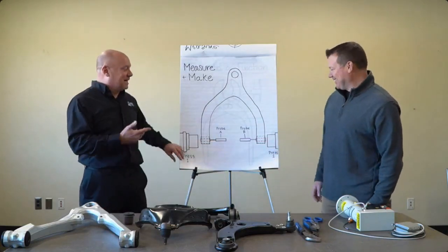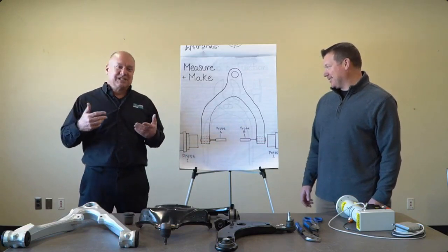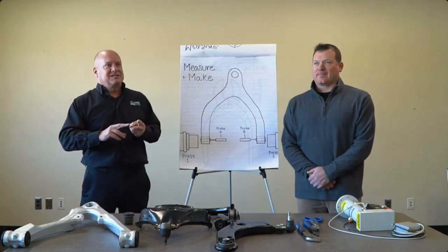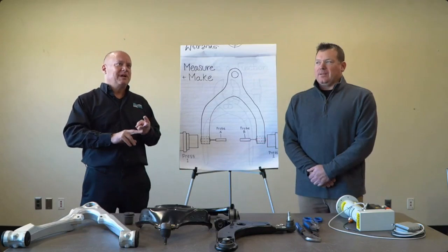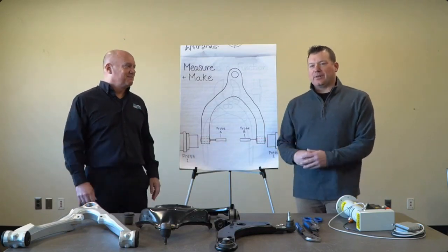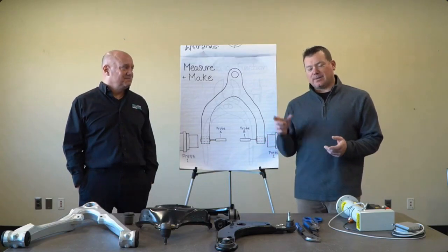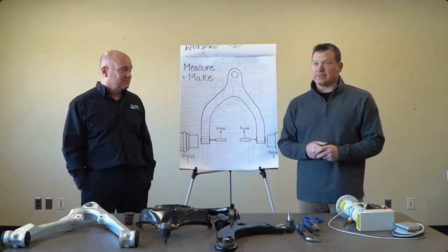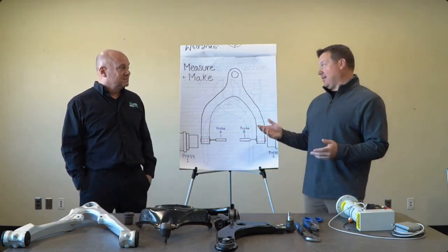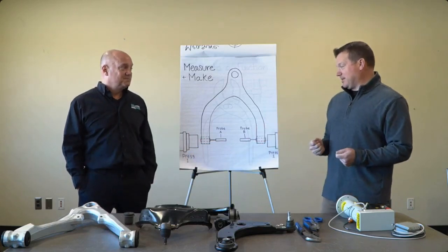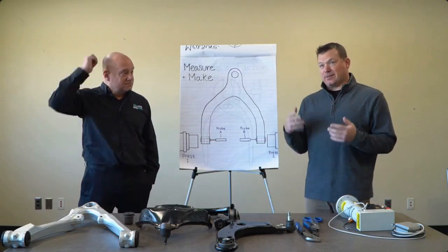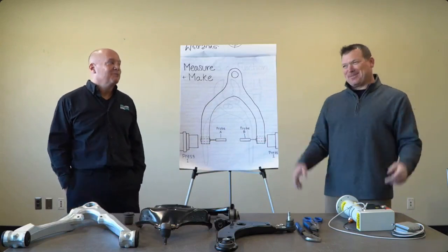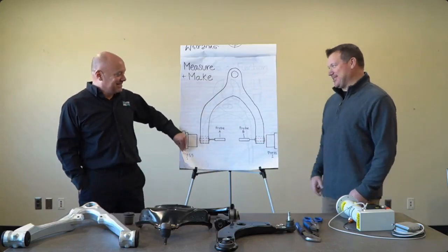Right. But so that is our measuring. We use this very similar technique in pressing armatures into motors, pressing stators, pressing impellers in the pumps, and a lot of times wherever there's some type of critical dimension you're trying to hold a tolerance to, and you generally see a lot of that on different part prints. But like Glenn said, those applications are pretty common for us, and we really pioneered that whole process. Our systems have these canned routines that are designed exactly for that. The canned routine for the measure and make is called the measure command. Pretty unique. Very creative with our naming. Yeah. Well, we're engineers, we're not marketing people.